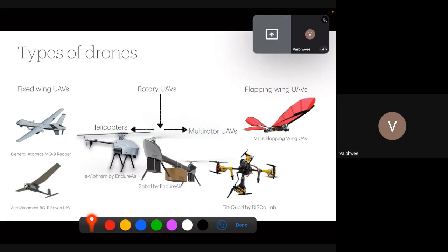The UAV is started with the propeller at the highest speed possible, and it is hand launched, meaning someone throws it by holding it in the hand, and from there it can take off on its flight. Such hand launched UAVs are usually belly landing. They land on their fuselage or belly, or at times there are capture nets on which they can be captured, whereas